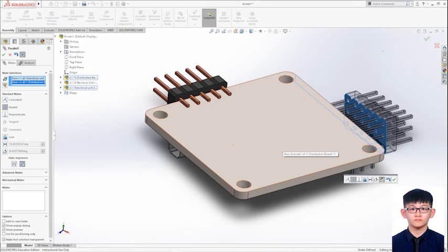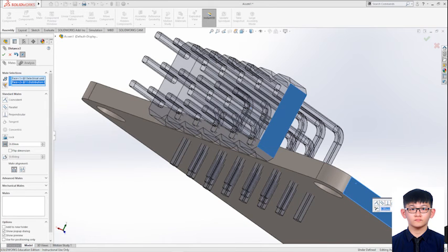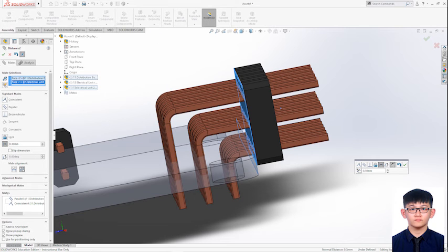Set the distance between the side of the electrical unit and the side of the electrical board to 8 mm. Then, set the distance between the side of the electrical board and the face of the electrical unit to 0.3 mm. After that, set the distance between the base to 1.5 mm.